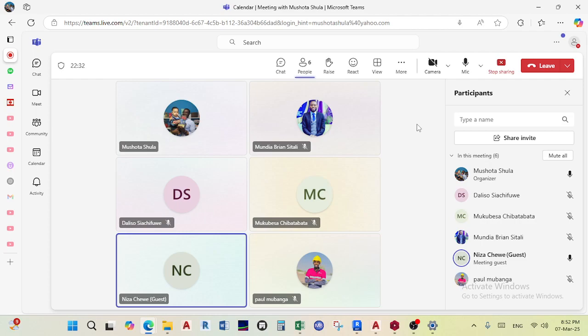The error it gave me said the members listed above are either fully unsupported or supported by beams or slabs. So these are the columns on the fourth floor, on the fourth story. That one is partially unsupported. If you know what causes this type of error, maybe you can explain it for us.